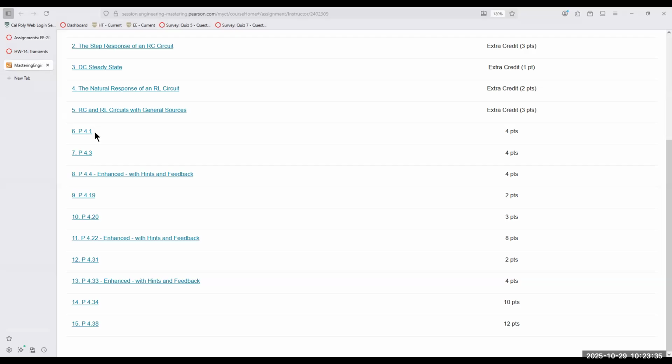It's fleeting. So transient response refers to the energy transfer portion between a source and the inductor or capacitor. Resistors are not energy storage devices. Inductors and capacitors are energy storage devices. So when you have a source in a circuit and you're sending energy into an inductor or capacitor, that energy transfer takes some time. It does not take place in an instant.